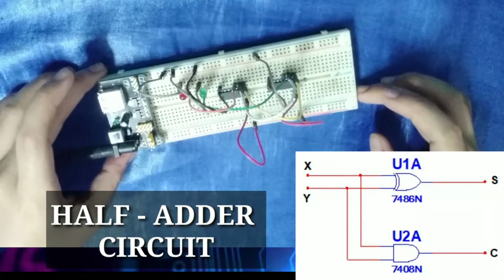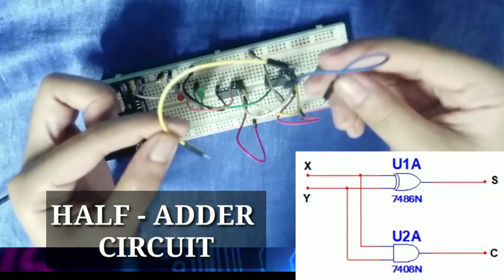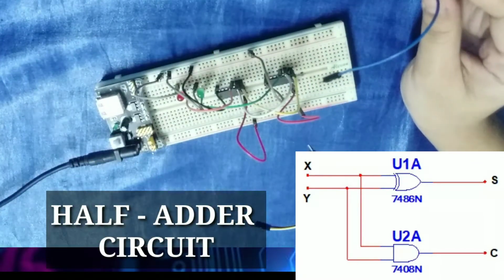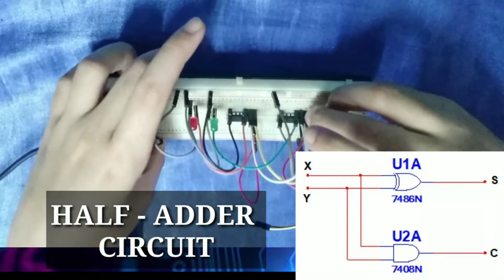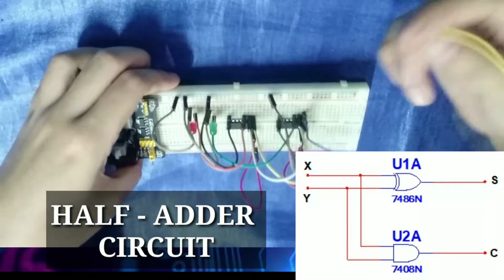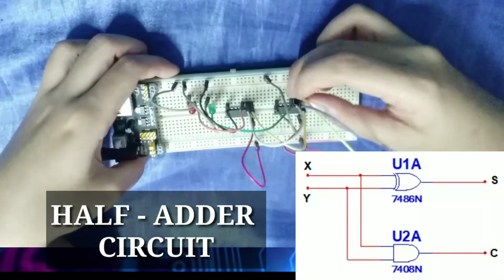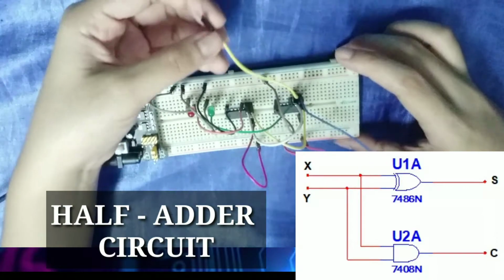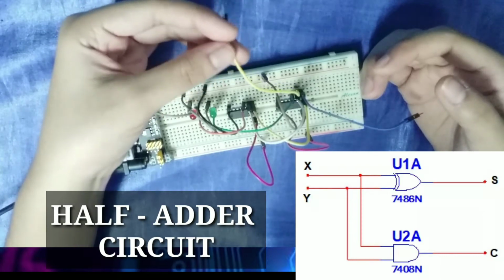Now for our sum and carry outputs, let's not forget to connect two wires for our inputs X and Y. Our input X will be on the first pin of our 7486, which is also connected to the first pin of the 7408, and the input Y will be on the second pin of our 7486, which is also connected to the second pin of the 7408. So X will be the blue wire and the Y input will be the yellow wire.